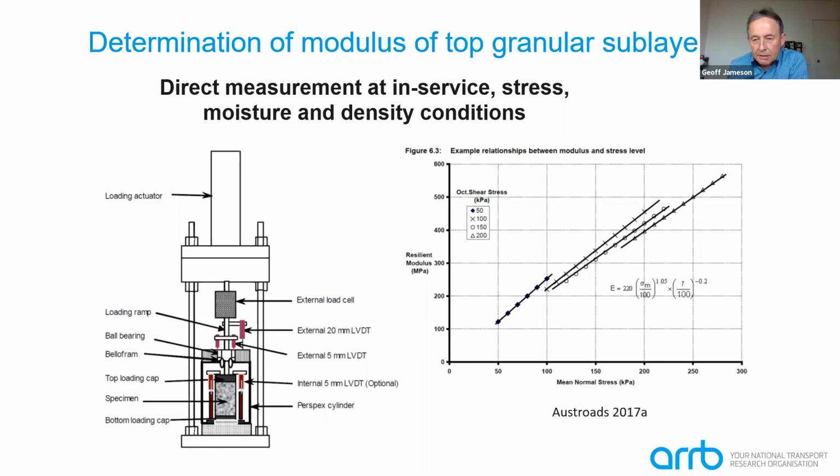It's not cycled, and it is considered as far as you can see there: the calculation of the mean normal stress includes confining stress as part of that calculation, and it also affects the octahedral shear stresses. So the model that we have includes the effect of confining stresses both through the mean normal stress and the octahedral shear stress.